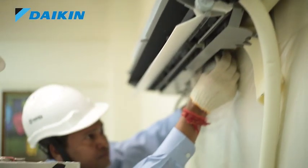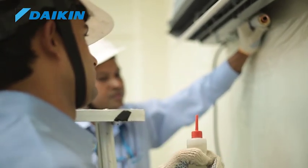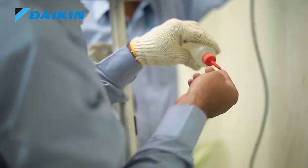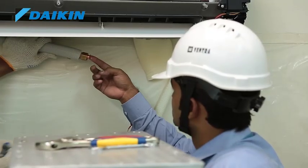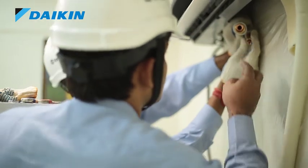Now connect the field pipe with the indoor unit. For this, first apply 1 or 2 drops of compressor oil on the internal surface of the flared part and also on the union. This oil will form a thin film on the surface to give the sealing effect.